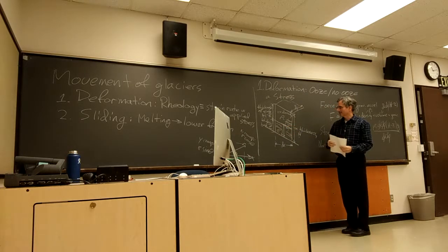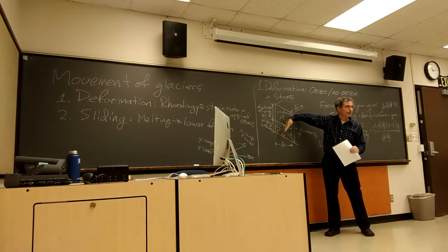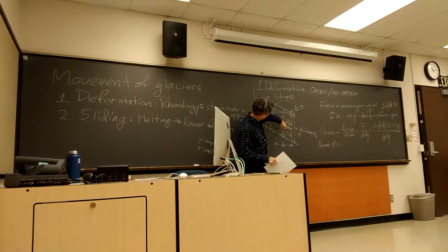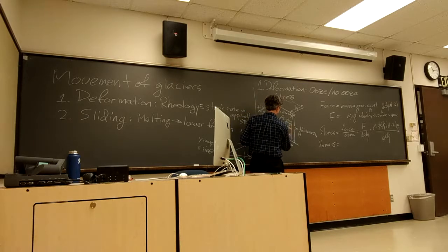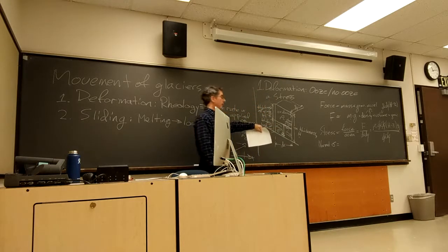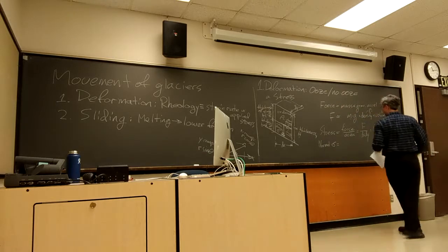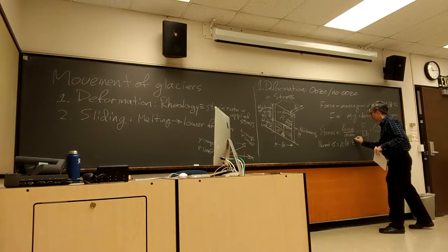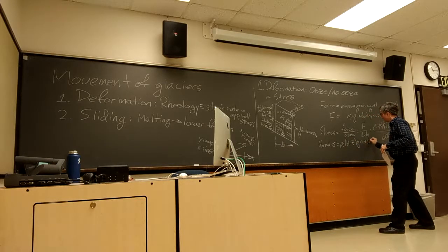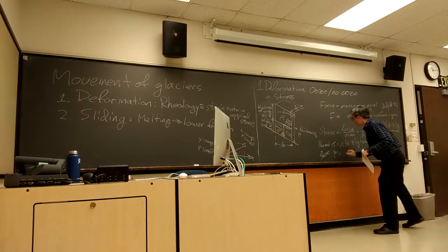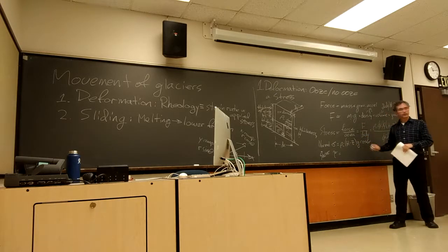If my axes are normal to the bed and parallel to the bed, then my angle theta is right here, and also there. So my normal component is my total stress times the cosine: rho (h minus z) g times cosine theta. My shear stress is the same business here, but with the sine.